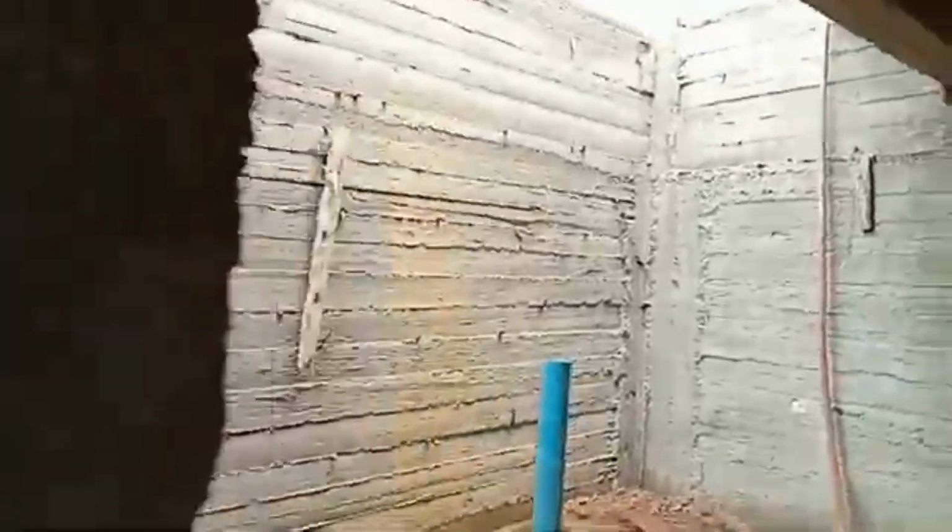Okay. And in some other case, if water is still coming, there you make a pathway for the drainage of the water, which is connected with all the paths and stores the water at one point. That point is called the sump. So you have to construct one sump.